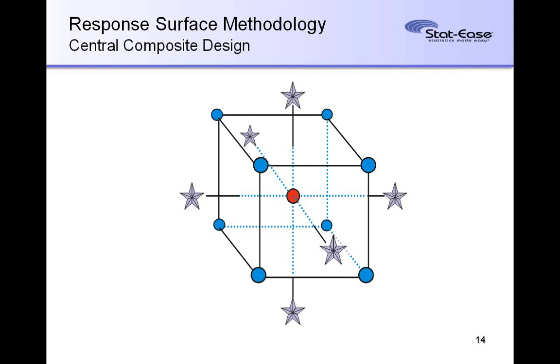And the defaults of the model graphs, if you've been using Design-Expert at all, the ranges are the factorial space, the plus and minus ones, and I know you sometimes ask questions about that, but that's because that's where the best predictions can be.